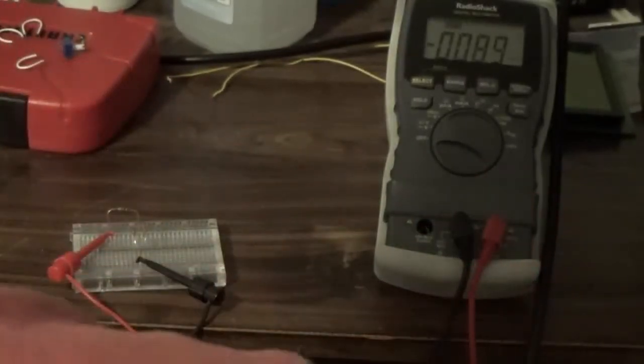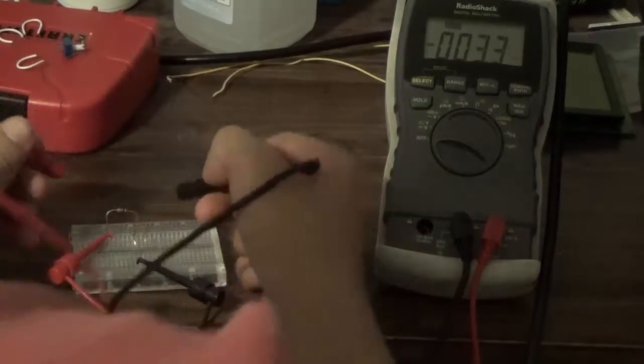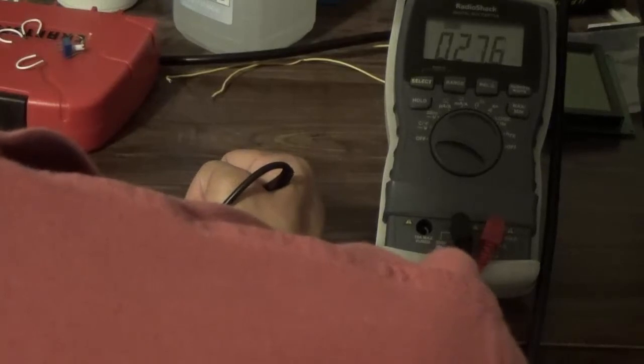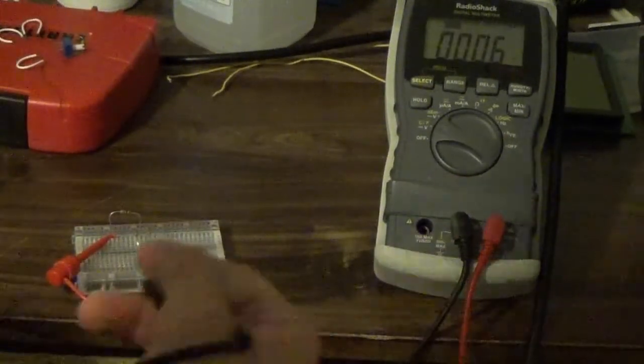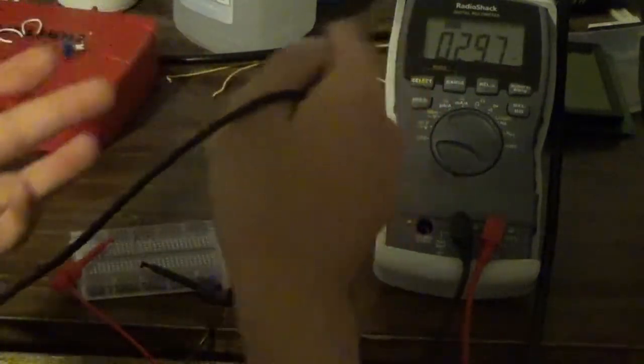And then we can assume that I have 5 volts applied over here on the source. We can assume that 5 minus that 2.2 is going to be what's here, and we shall see if that is true. If it'll ever measure for me. Please measure. Come on. There we go, 2.9. So this source is probably dialing in at about 5.1. I can check my meter. Yep, 5.1. So 2.2 plus 2.9, 5.1 is what this meter is saying.